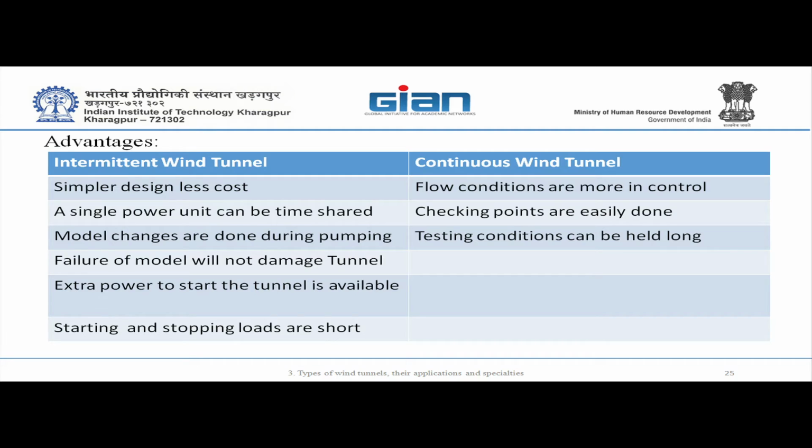Now the in-draft over the blowdown. With in-draft, when we are sucking from the atmosphere, you have constant pressure, as bad as it is, but it's constant. It's standard pressure. There is less contamination, because when you come from a compressor and storage tank, usually you have pebble beds and all kinds of stuff that will blow with the air. When you suck from the free air, it'll be clean. Starting and stopping loads will be smaller because you're running with lower pressure usually.